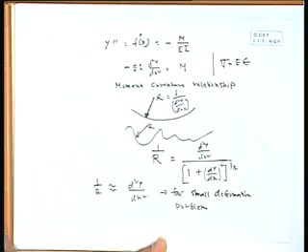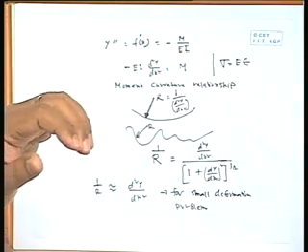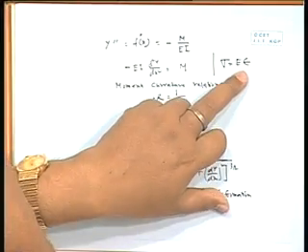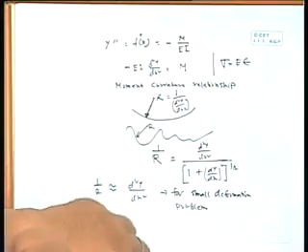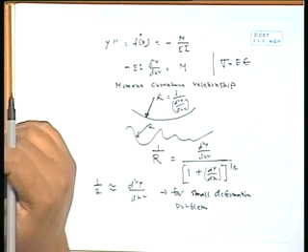Moment is nothing but one of the stress resultants, because throughout the depth of the beam the bending stress will vary. It will be maximum at one extreme and 0 at the neutral axis. So the total effect, if you take it, is basically the bending moment. So M is the resultant of the stresses. That stress resultant we can compare with stress, strain we can compare with the curvature, and E here is something related to EI.